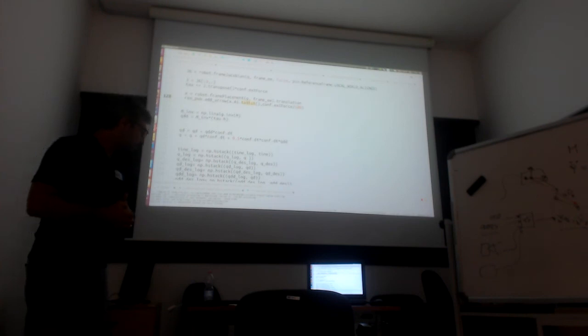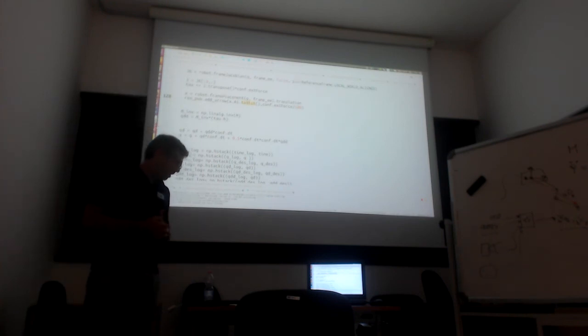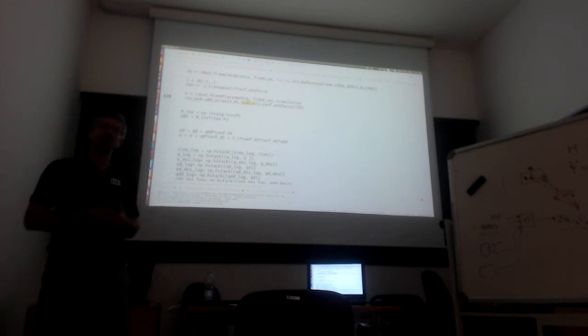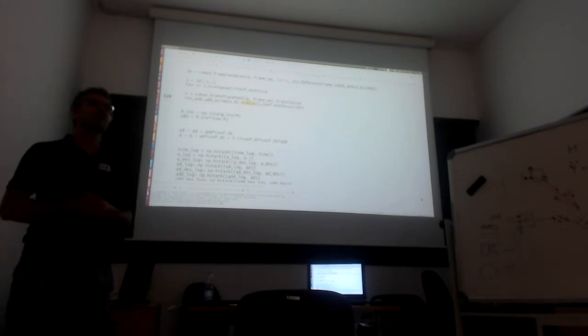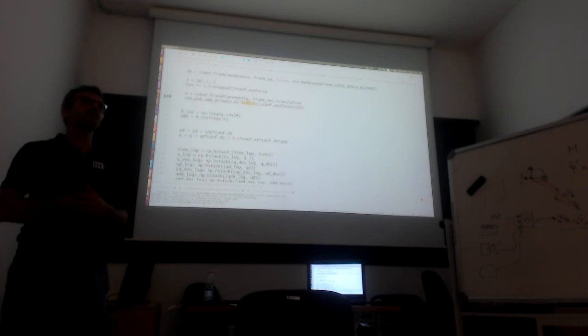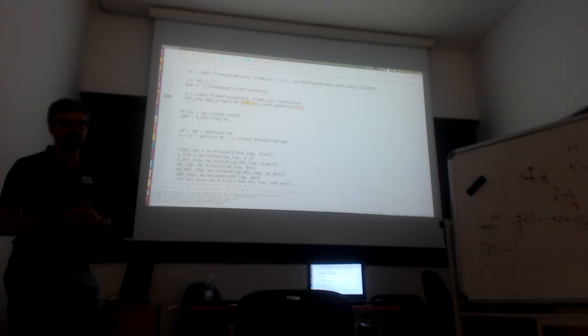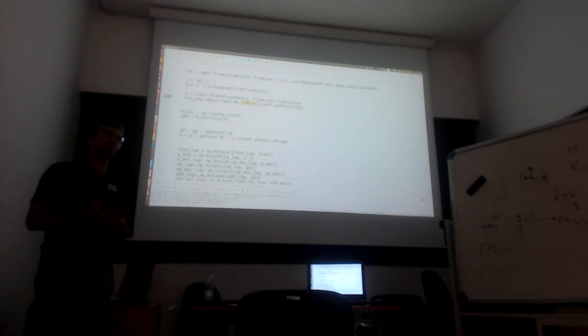Then we discussed some limitations of the implementation of this algorithm that are due to non-idealities in the controllers that depend on the kind of sensor we use, encoders, quantization noise, minimum speed that you can measure, and also we talked about friction forces and how to deal with that, discussing that it's better not to compensate directly but to measure the torques at the link side with a torque sensor or with a force sensor.